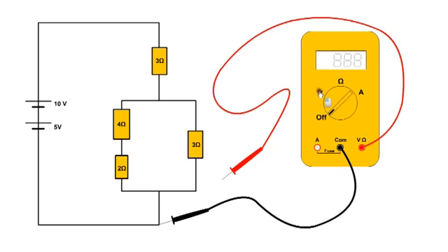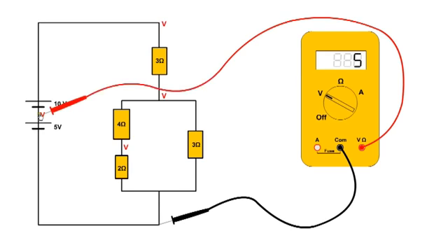When voltage is selected, we measure 5 volts and 15 volts. For the purpose of the demo, we assume the conductor has no insulation. The voltage at this point is reduced to 6 volts due to the voltage dropped across the resistor and further reduced to 2 volts at this point.